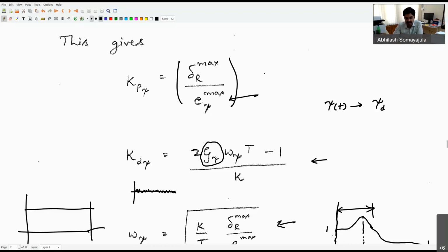Now we will take a look at a second version of this, where we are trying to use our guidance law in terms of the cross-track error between the two waypoints. So if we are going from one waypoint to the other waypoint, how far away from the track am I? We want to minimize that cross-track error to 0. And we'll see that that can usually be done with the guidance laws that we have developed, right?